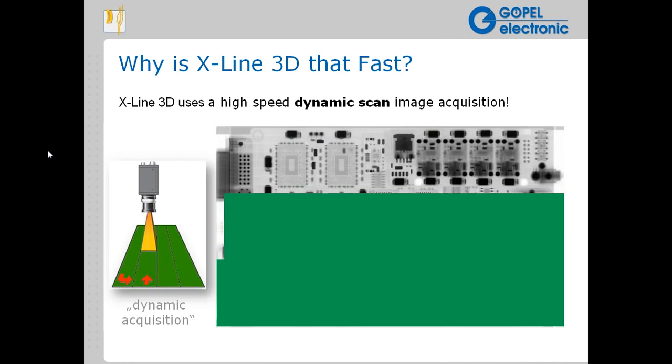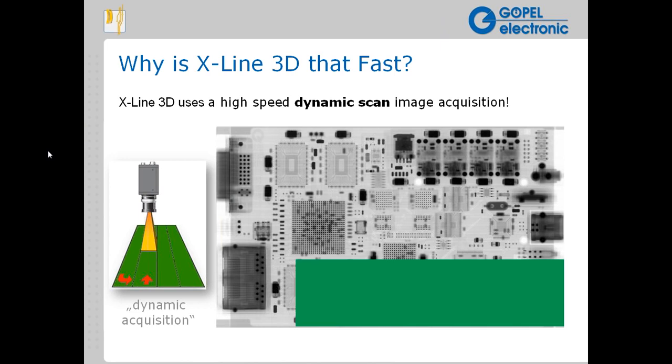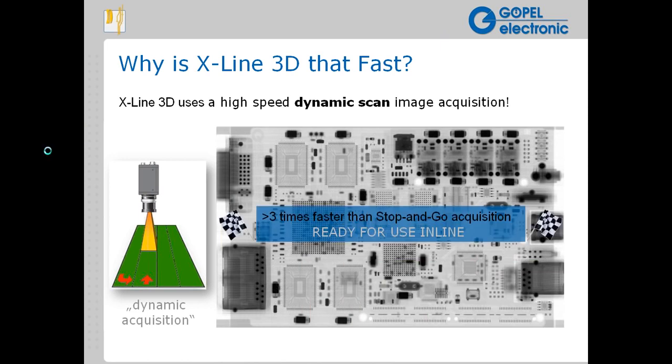One other reason why we are so fast is the Opticon X-Line 3D system is really not intended as an optical inspection system. It's not intended for visual, high-resolution X-ray analysis, such as a CAT scan system or that sort of thing. We optimize speed and resolution. So we go to the resolution necessary to create detection, necessary to avoid false calls, but we stop there for the sake of speed. So we are always looking for that optimum combination of speed and resolution for the inline production application.